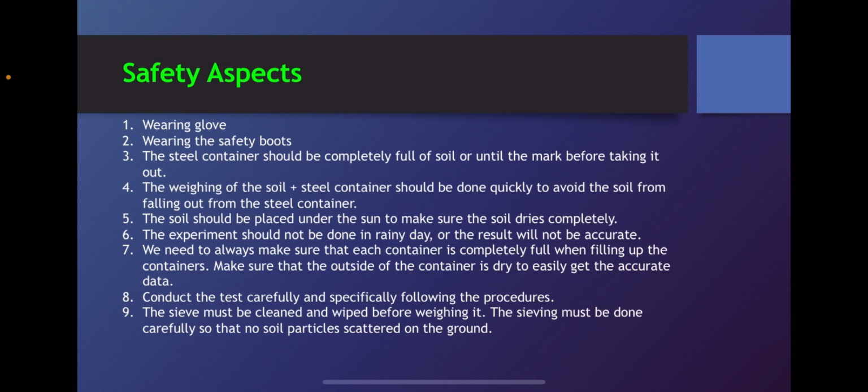Next, we need to always make sure that each container is completely full when filling up the containers. Make sure that the outside of the container is dry to easily get accurate data. Then conduct the test carefully and specifically following the procedures. Lastly, the sieve must be cleaned and wiped before weighing it. The sieving must be done carefully so that no soil particles are scattered on the ground.